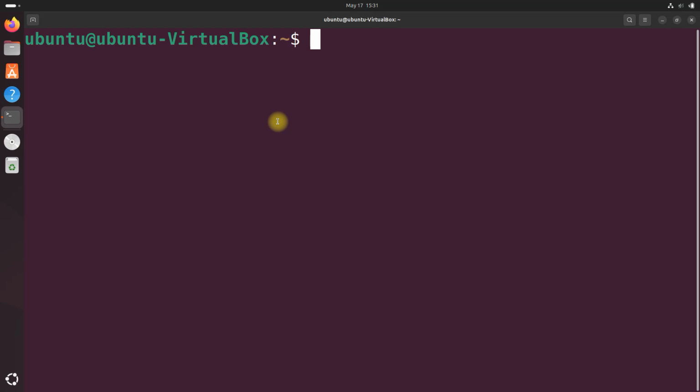inside the mecanum parameters node. And if we want to change it, we're doing it by the command line. But how do we launch our node so that it has our desired parameters that it pulls from a YAML, a text file?